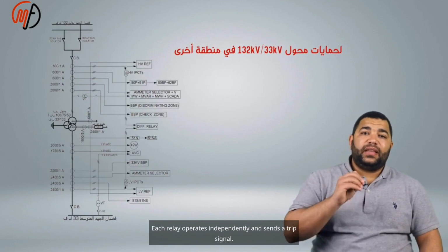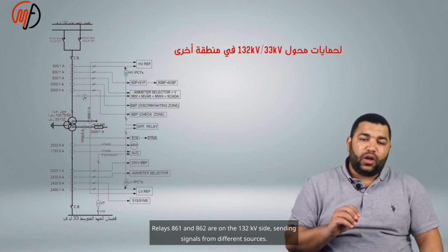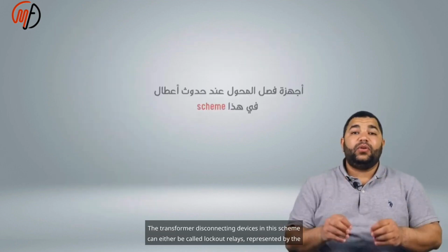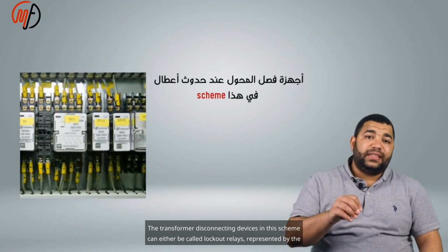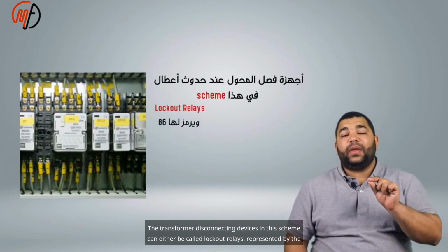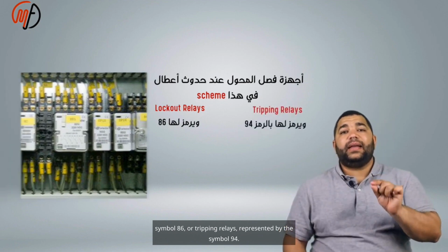Each relay operates independently and sends a trip signal. Relays 86T1 and 86T2 are on the 132 kV side, sending signals from different sources. The transformer disconnecting devices in this scheme can either be called lockout relays, represented by the symbol 86, or tripping relays, represented by the symbol 94.